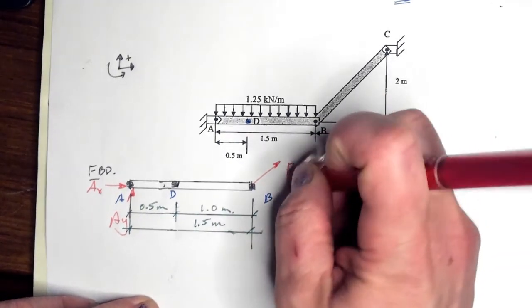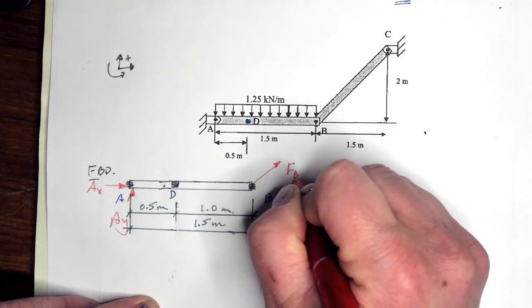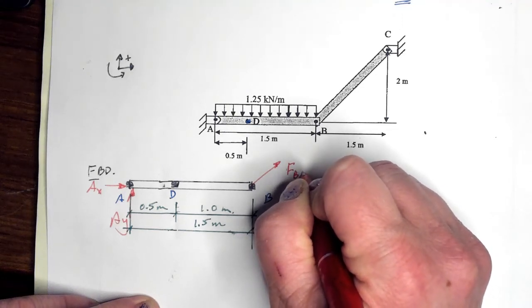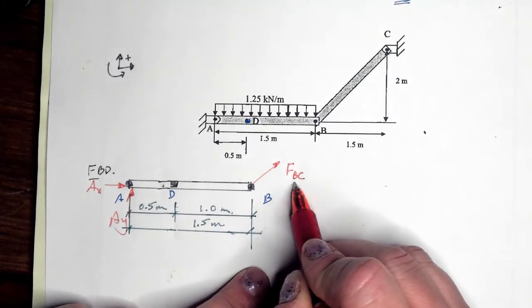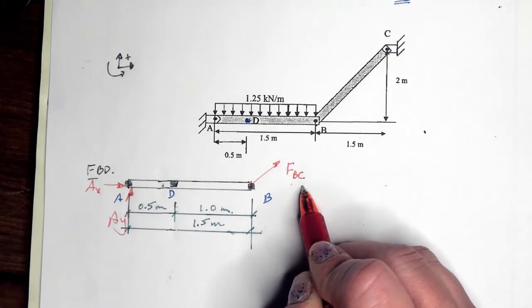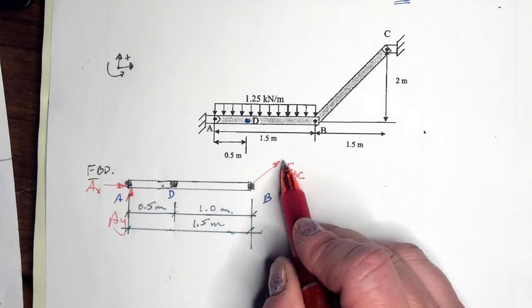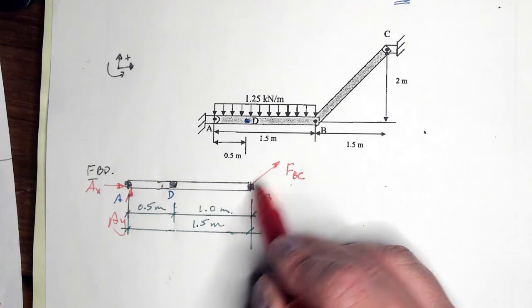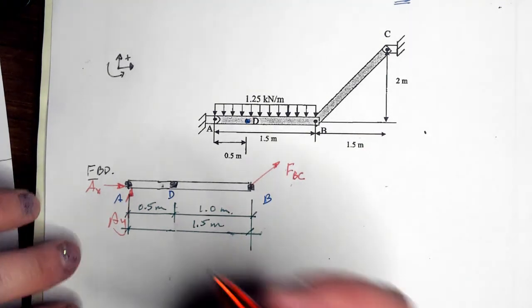Let's call it force at the member at the point where we're going to go from B looking at C. So that's the way we'll do that. We start looking, sitting on B, looking towards C. That's the direction we're looking. I'm drawing it outward, tension, just as positive notation, and we might find that it is different than that.